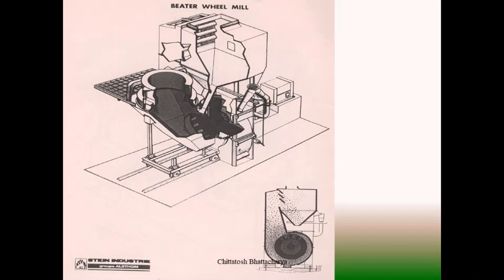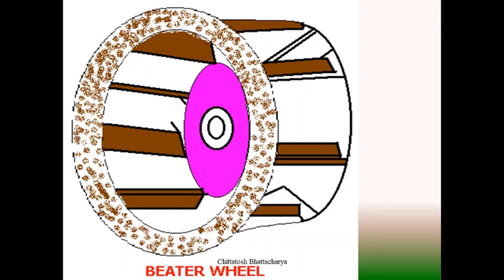So due to impact, whatever coal is dropped into the system gets ground, and that is carried instantaneously with the hot medium through the mill outlet, and there it gets classified. Heavier particles return to the feeding pipe, and the remainder goes through the classifier zone and through the coal carrier pipe.